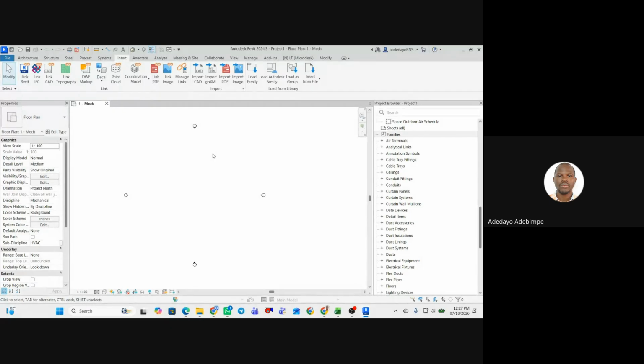We are going to use this particular year of Revit, so that you avoid any conflict of whether I can save as or not. Because the truth is, if you receive a 2023 file and you use 2027 to access it, fine, it will work. But the moment you save, the people with 2023 can no longer access it. So that's what I want to clarify.